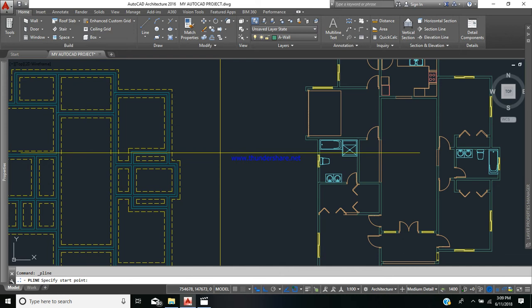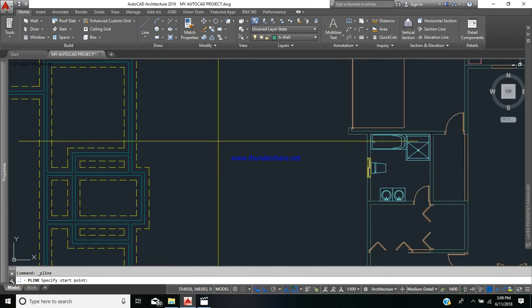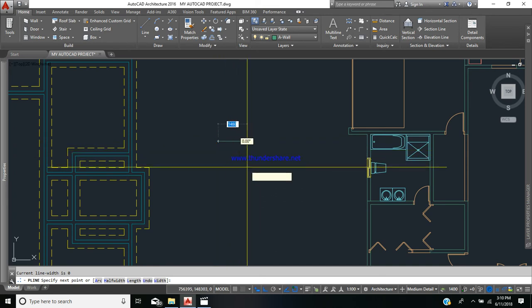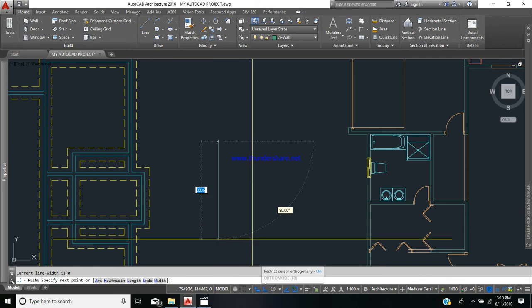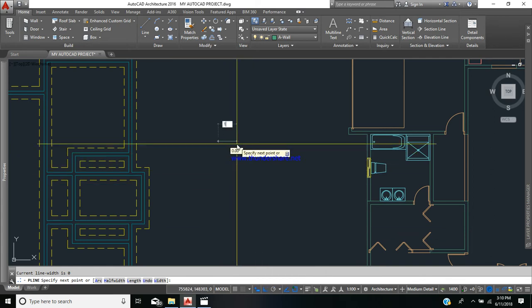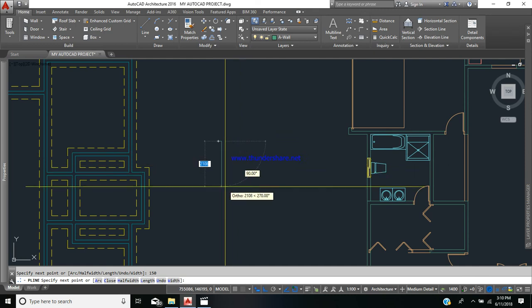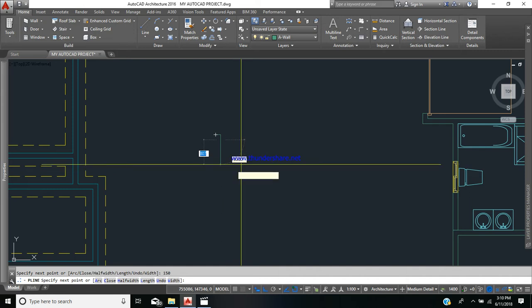Alright. Now the basic dimensions for an L stiffener, I'm going to click on my screen, ensuring that my ortho mode is actually on. Now I'm going to go in this direction 150 millimeters, so I type 150, give an enter. I'm heading in this direction 150, give an enter as well.